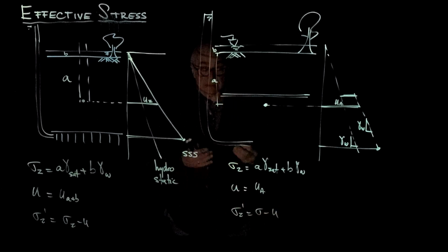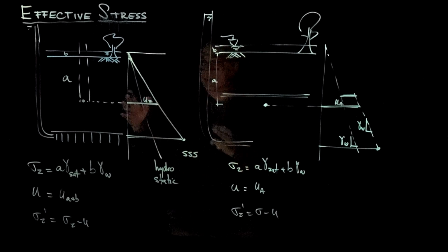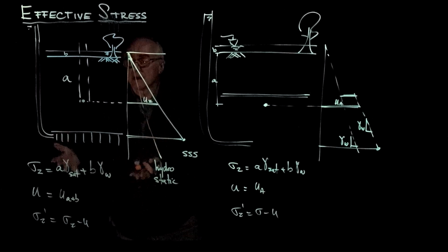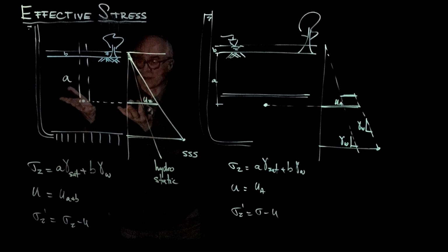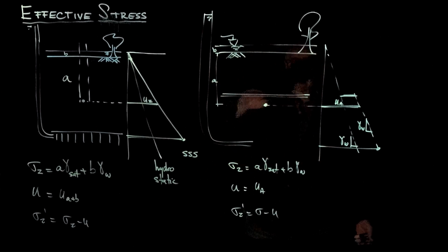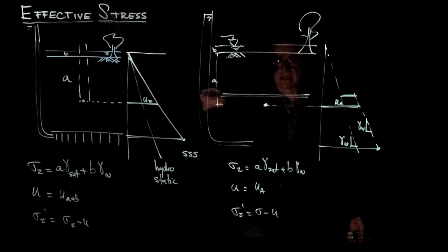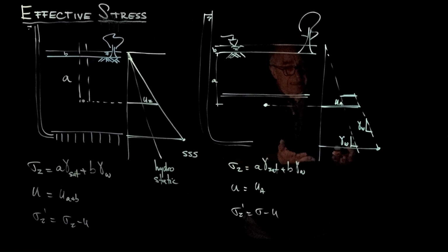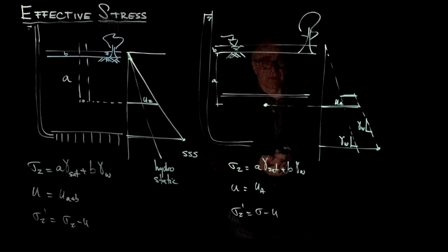What is important to recognize is that in this case, whether it is steady state seepage, an Artesian elevation is lowering the effective stress. In this case, it's hydrostatic because there is an aquitard, a thin layer of clay that is preventing the fluid flow. But if that is the case, it's pushing up the sediment above the point, and is lowering the effective stress at the point.